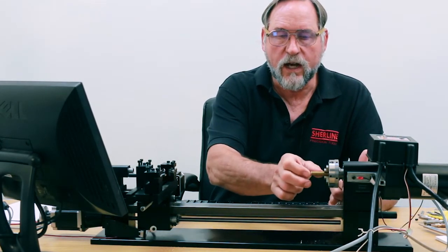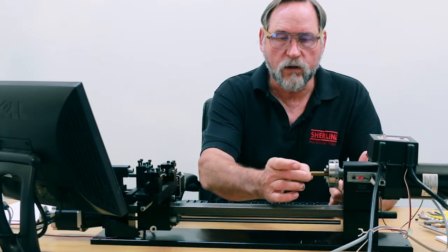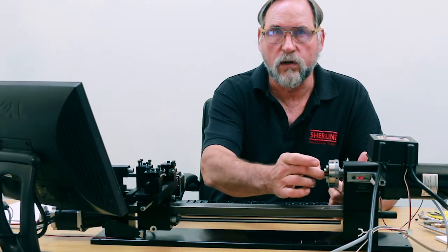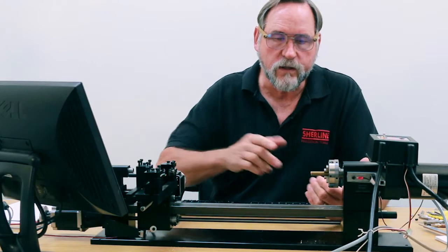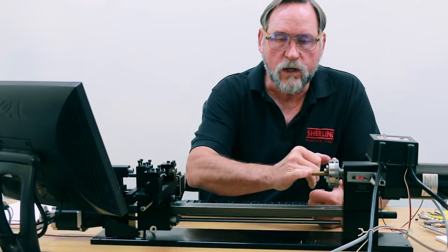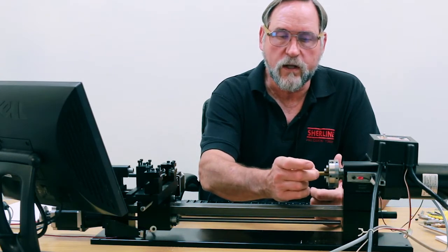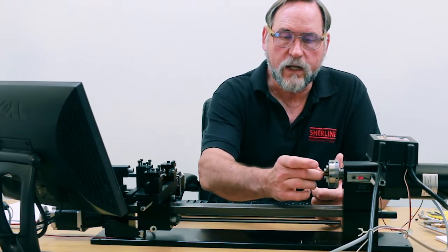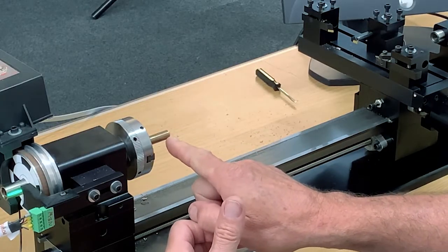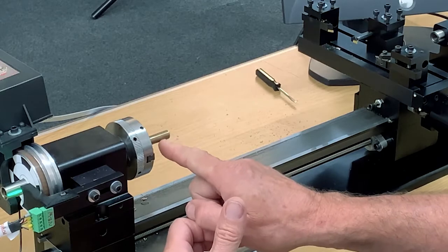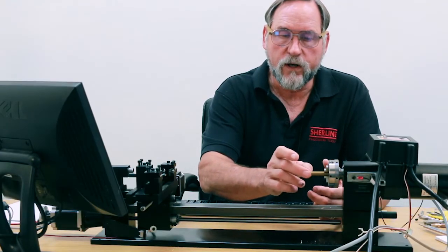You're not only sticking out too far, but now you've whittled your stock behind the larger area of your cut down smaller. So things are going to go south on you really fast. The way you would run this ideally, since this part is going to be threaded, then a 1/4 inch diameter, then a 1/8 radius to a 1/4 inch diameter, is to rough turn and rough thread the threaded section all the way out here, then finish turn and finish thread.